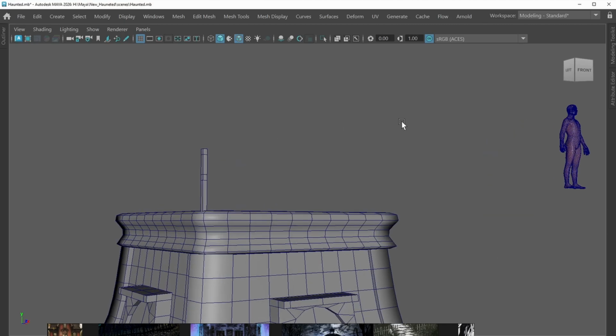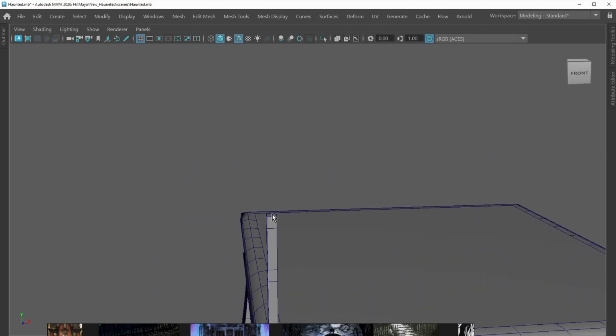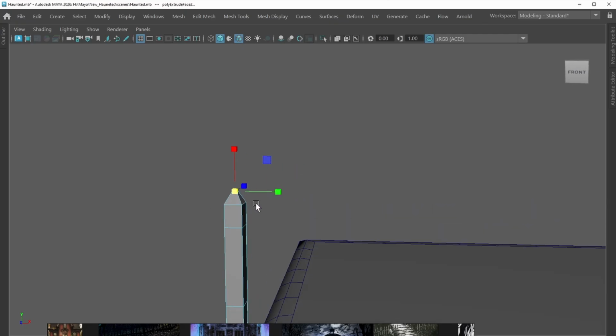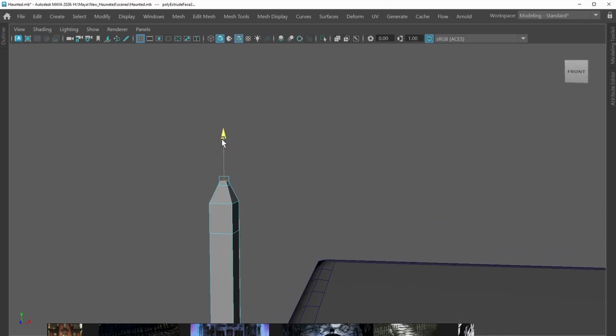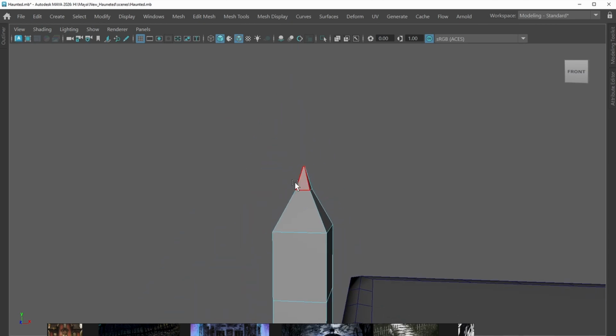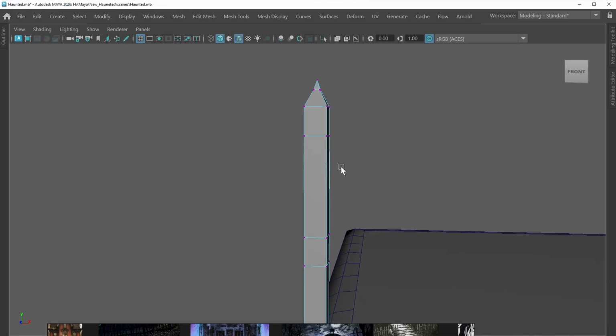And that happens all the time in 3D modeling, you kind of decide what else you want to do. Because I think I'm going to extrude this and then make it kind of pointy like that, I'm thinking. Maybe do another one like that. So I'll leave that on top here. That will work. And then we'll take this and merge those together. And the way I'm doing this again, I select all these, shift right mouse button and merge like that. That looks good.